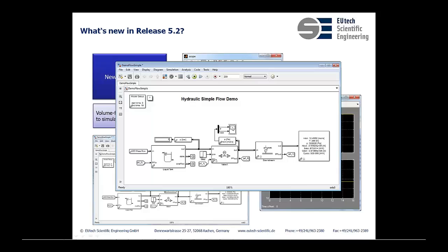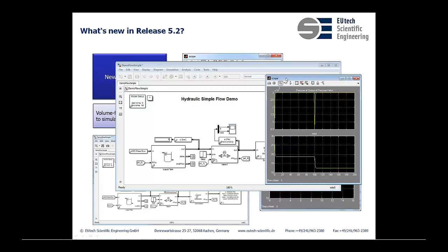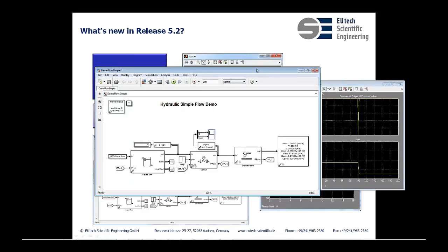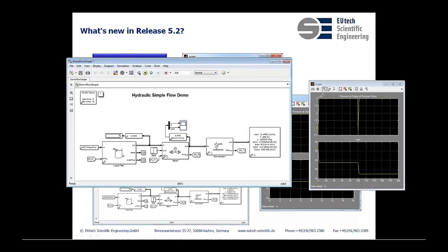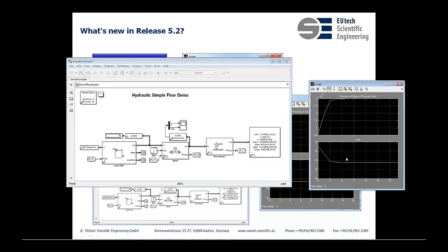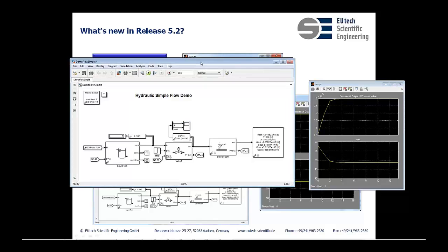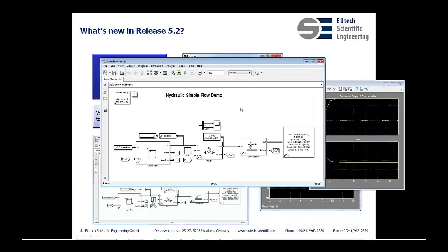okay, let's look at the pressure and molar flow in the network. So this is what we have. You can see here up front, there is a little bit of a transition. This is what I meant with the numerical transition. This transition would not be there in real life, and it can lead to confusion in interpreting the results of a simulation. So to solve this issue, we can reprogram this model as a volume in the volume flow volume method.